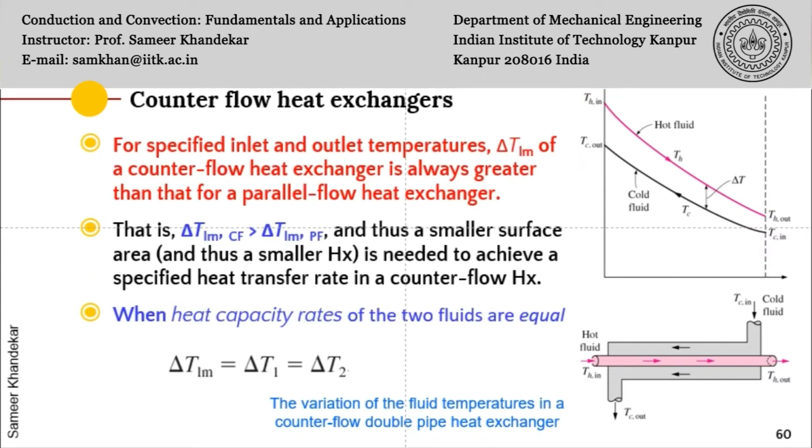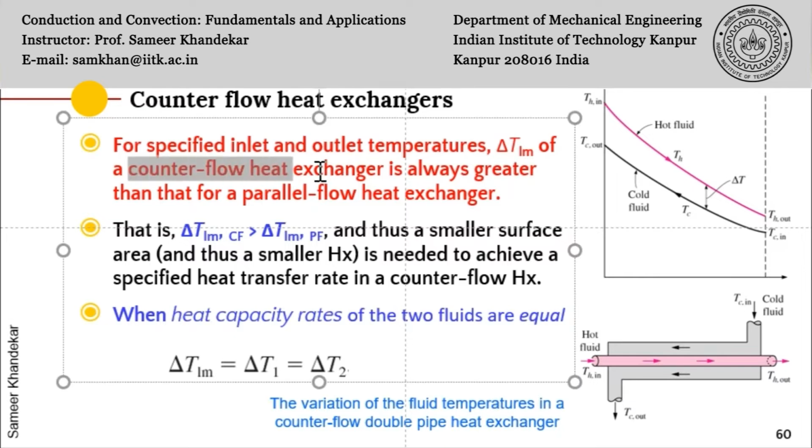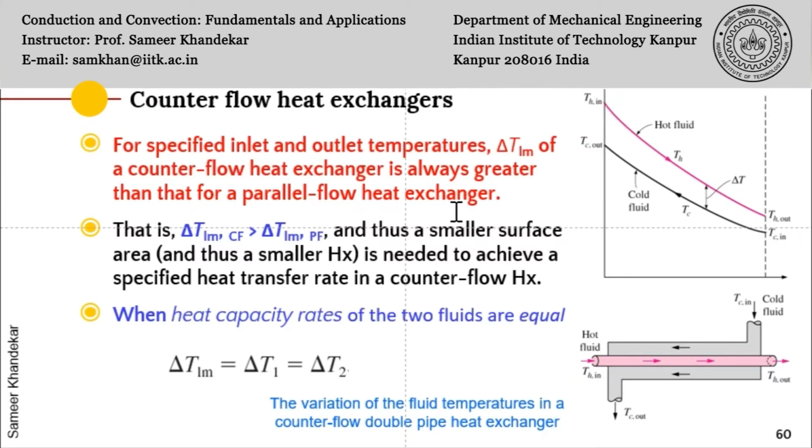So moving on to slide number 60, we should also note that for specified inlet and outlet temperatures, the logarithmic mean temperature difference of a counterflow heat exchanger is always greater than that of a parallel flow heat exchanger.